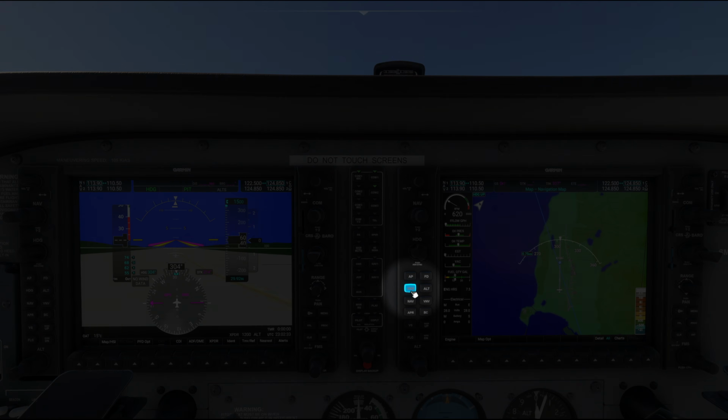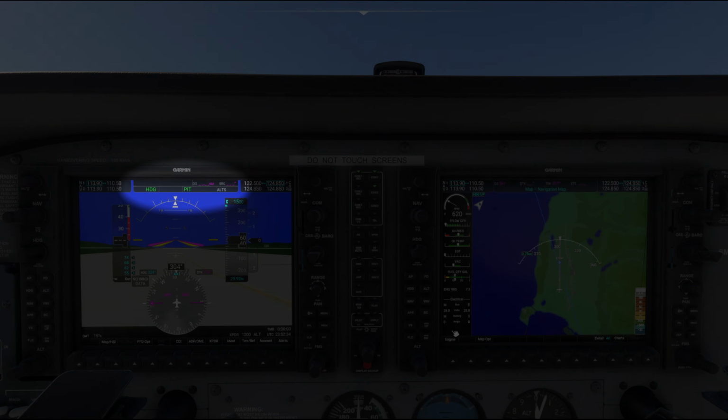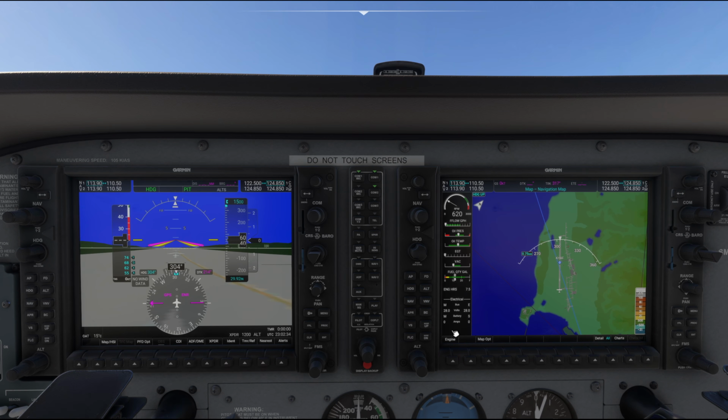You'll see the annunciator panel at the top of the PFD, also called the scoreboard, change to show HDG and PIT in green and ALTS in white. This means heading and pitch are being held and altitude is being selected. Notice that the box in the middle between HDG and PIT is empty. This means that we're in flight director mode and the autopilot has not yet been engaged. When it's engaged, you'll see AP here for autopilot.